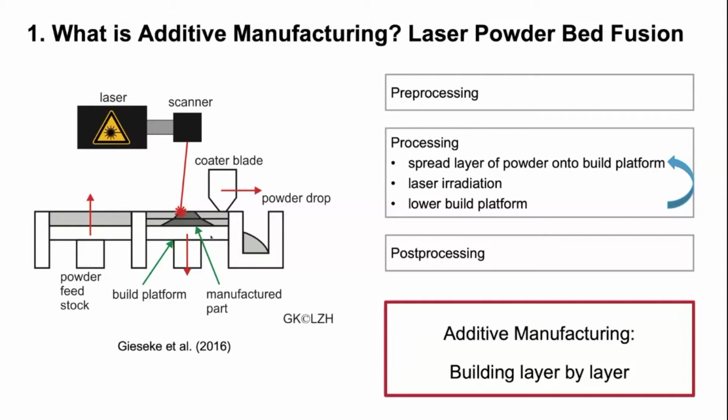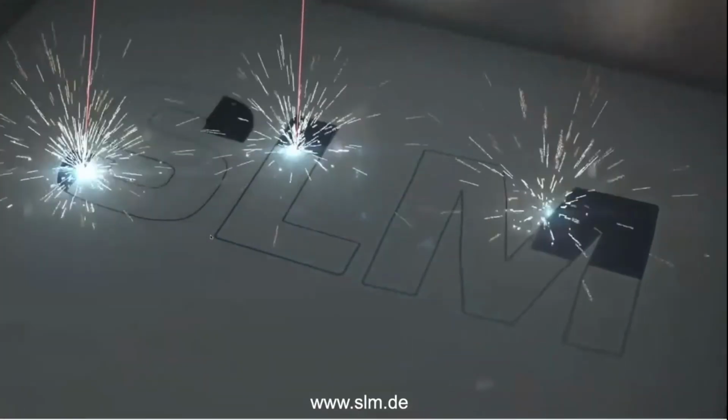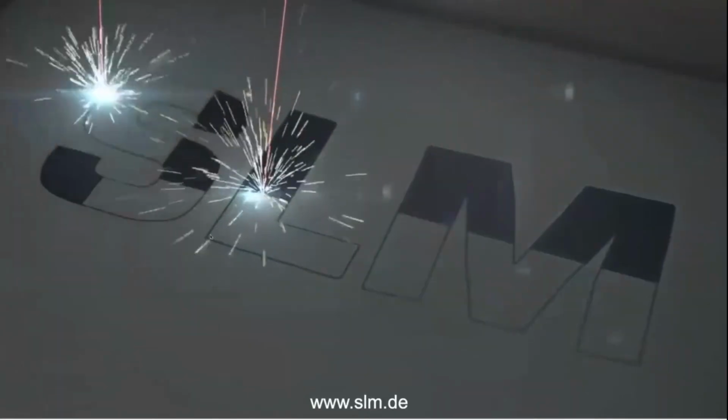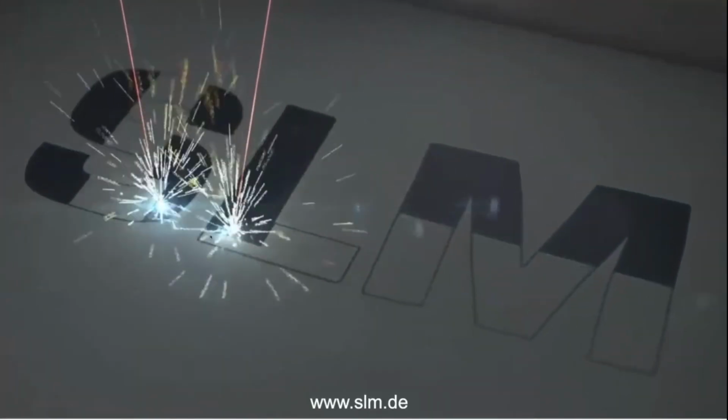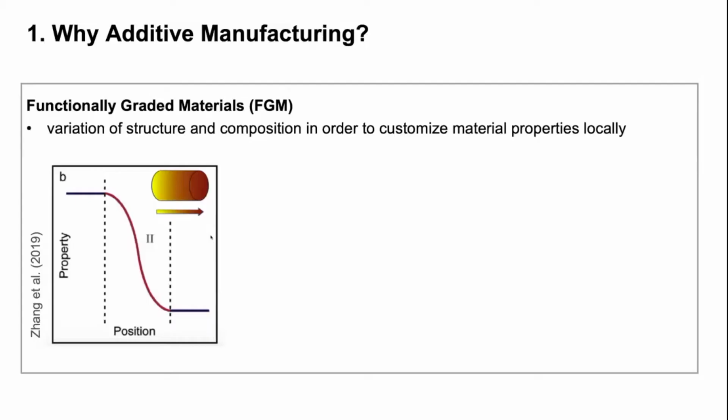Post-processing, first of all, includes the removal of unnecessary powder. Then we have optional heat treatment, polishing, whatever is desired and necessary. Here's a video of the process. We see a powder bed which is partially irradiated by a laser, and once this layer has been processed, a new layer is added, and this process is repeated until the part has been built.